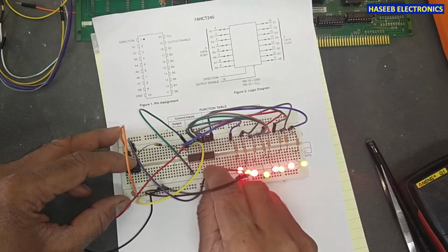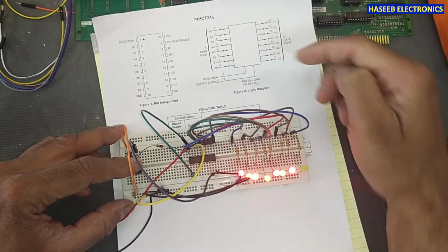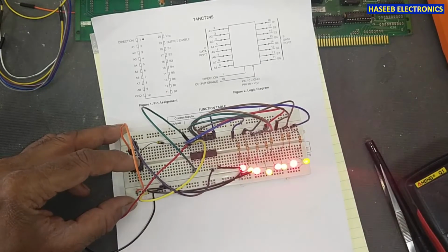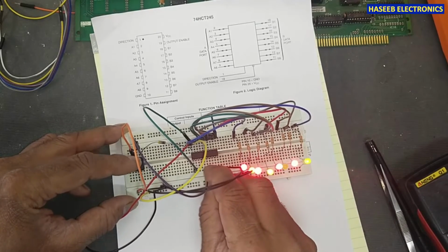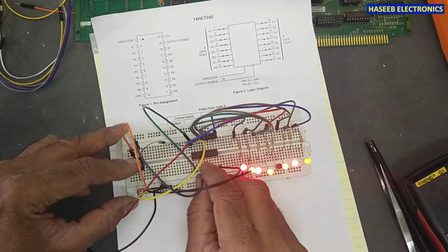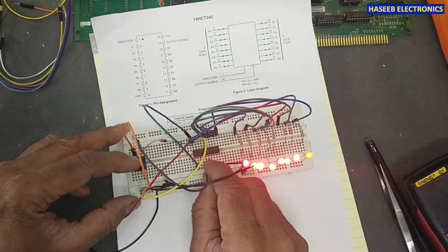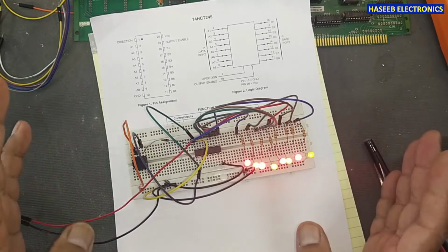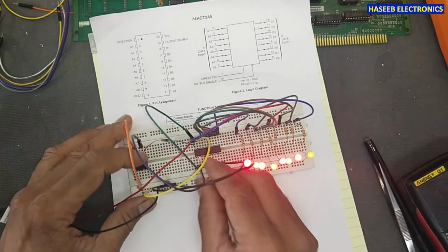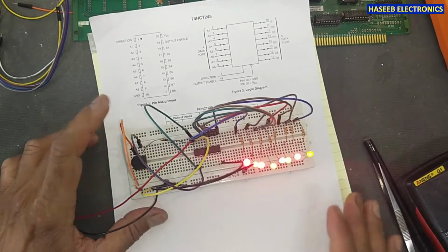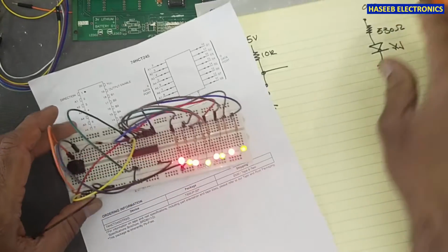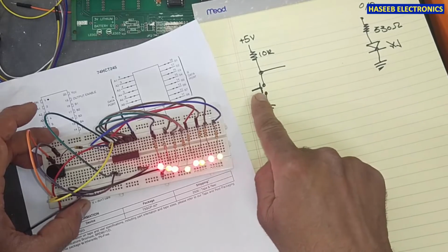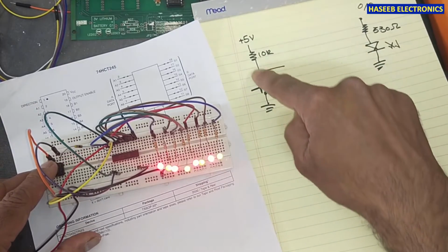Now I will connect to the first pin, pin number 9 here. It is changing now. I will move input to pin number 8. It is working good. If any pin gets stuck in that condition, that port of the IC will not work. Using this technique, we can test the IC very simply. When we push this button, we are giving a low signal. If the push button is off, at that time it is a high signal.